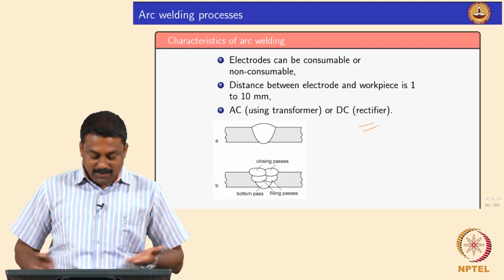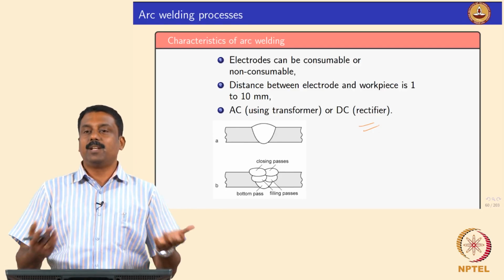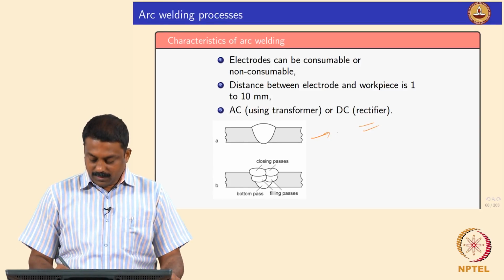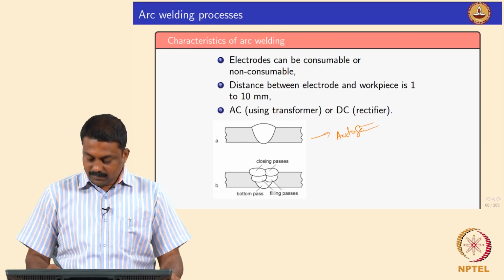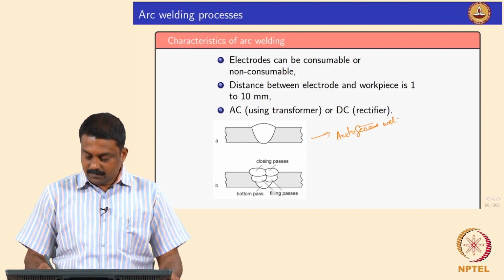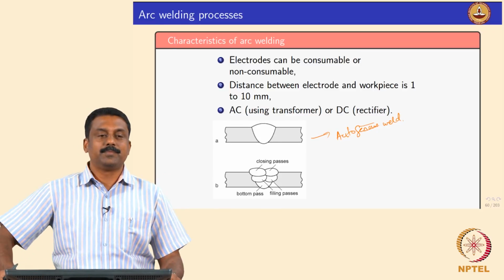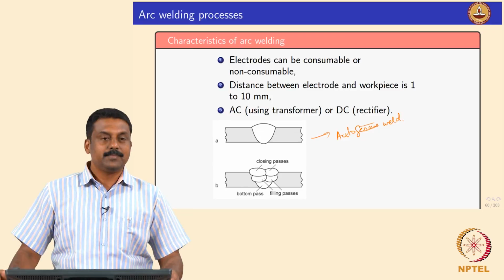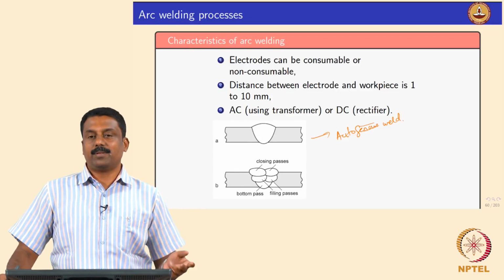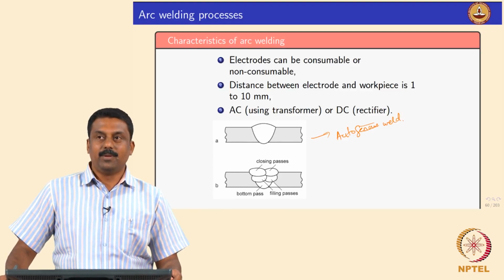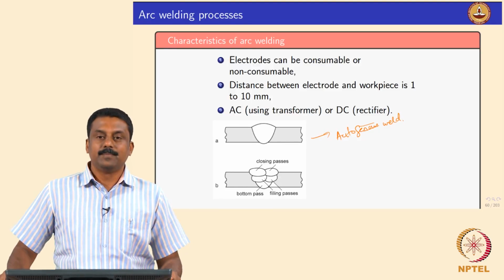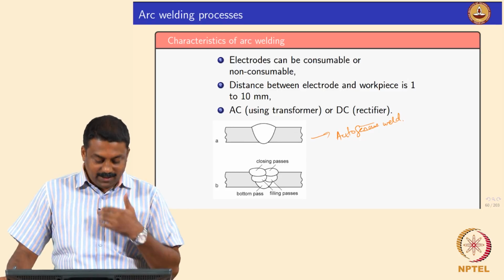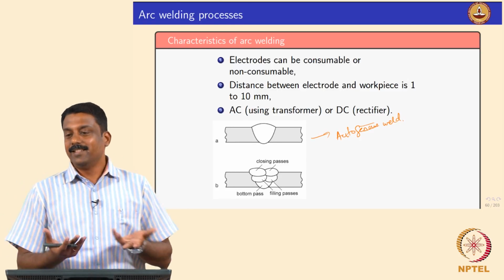Now if you want to weld, obviously you can also weld without a consumable, that is known as autogenous weld, so welding without consumable. Or you can also use a consumable to fill the weld cavity, so then it is a consumable welding process. You can use it with various numbers of passes. If you appreciate the beauty of the physics, then you can also talk about the field.